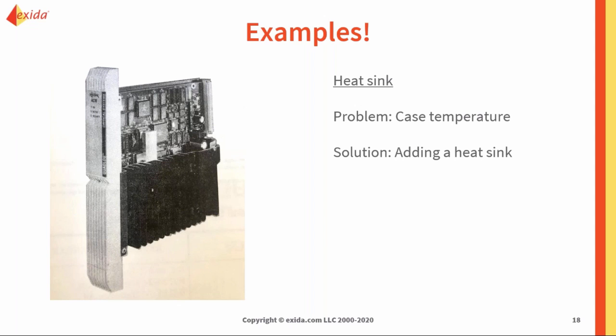So we were able to go back into the FMEDA and look at what failures were due to overheating, especially those dangerous failures due to overheating, and reduce a lot of those. So although the engineers knew adding parts was going to be costly and redesigning it was going to take time and cost, they decided it was worth it to bring to the market a more reliable product. Thus, they brought a product with lower failure rates.